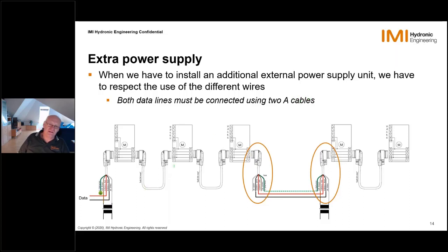And therefore, you can use 2 A cables here, or cut a B cable, whatever you do. That would be the same. And then you are connecting the end and the begin of these parts. You can feed the power supply to the brown and white cable here. And then, of course, the data are transmitted here, and the rest is interconnected.